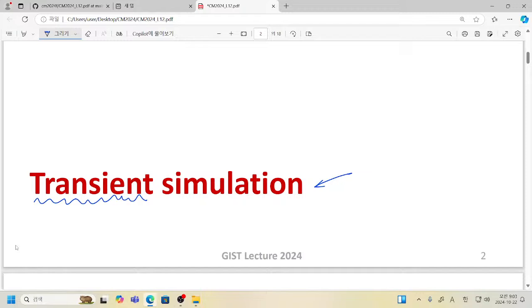If you are working with device simulation, in many cases your first characterization method is not this time dependent quantity. Let's say that you have a MOSFET here. To characterize this device, you first draw certain IV characteristics, of course drain current as a function of your gate voltage.